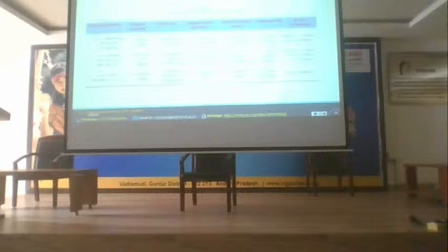And also, as I said, based on the available power levels we have different chargers: level 1, level 2, level 3. What is level 1? It is like onboard. Level 2 is also onboard, but the power ratings are different. Don't get confused, both are onboard. Level 3 is outboard. Right. You see that level 1 is only for single phase. Level 2 is for both single phase or three phase.